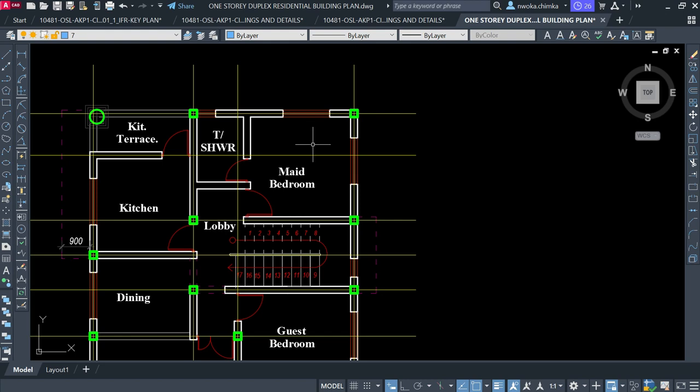Now, if they go ahead and build that structure, and maybe that structure isn't standing, what happens is that if you want to overcome that, you either go and increase your slab depth. Can you hear me? Okay, you either go and increase the slab depth of that panel from 150 to 175 or 200.